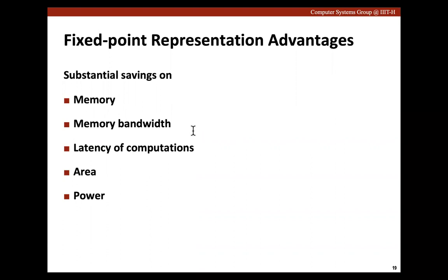There are many tools that are being built. Again, this is an important and very hot area of research. When we are trying to squeeze performance, there are many dimensions to look at, and bit widths are a very important dimension to consider. It will have an impact on area, DSPs used, flip-flops used, FPGA slices used, power consumed, and so forth.